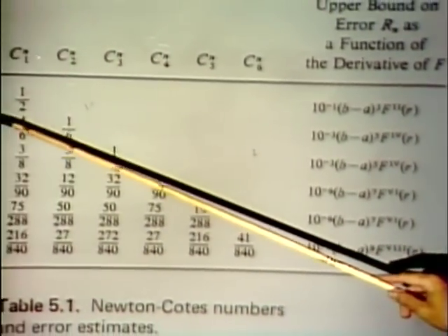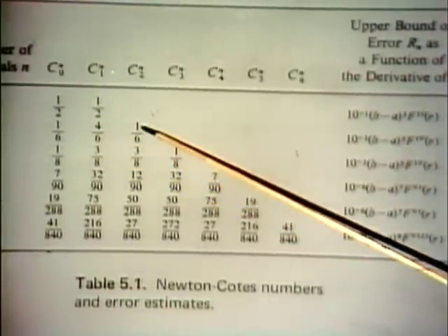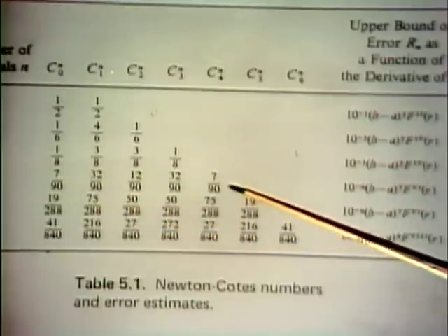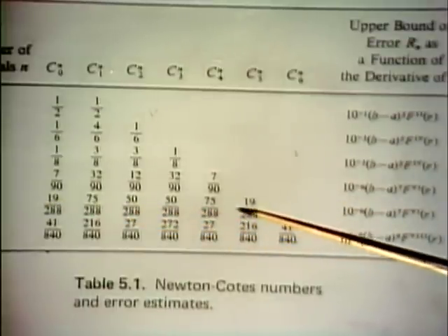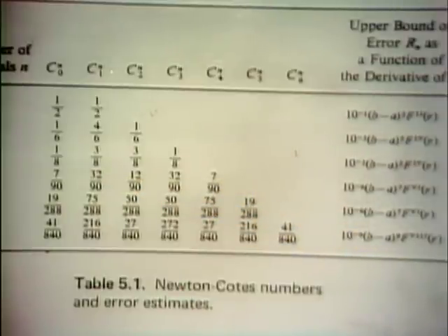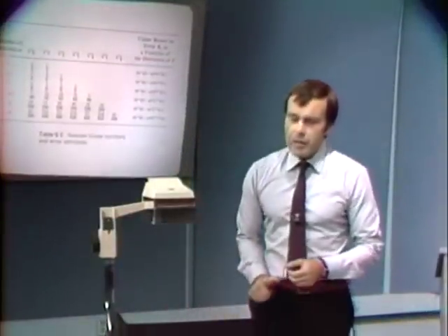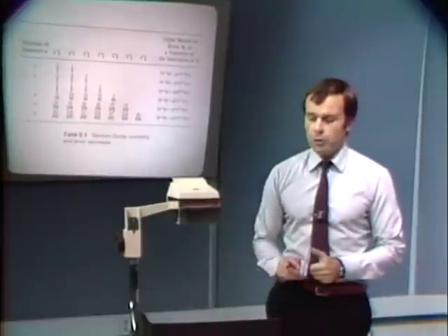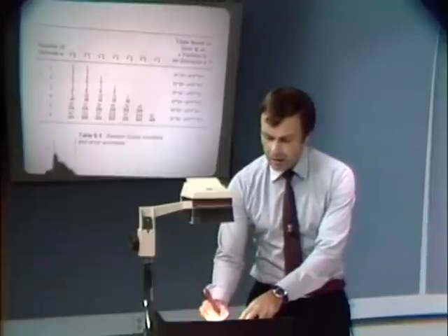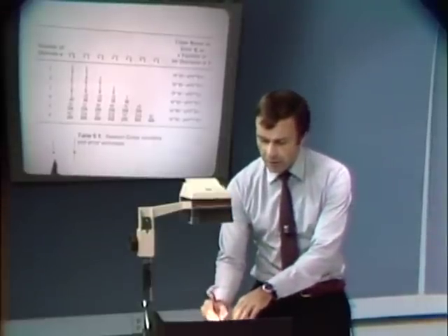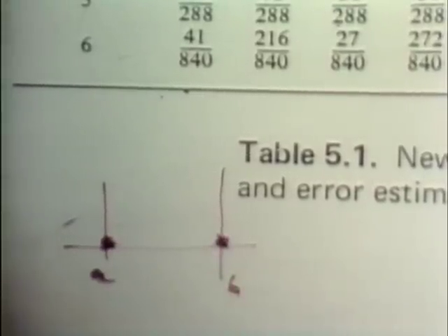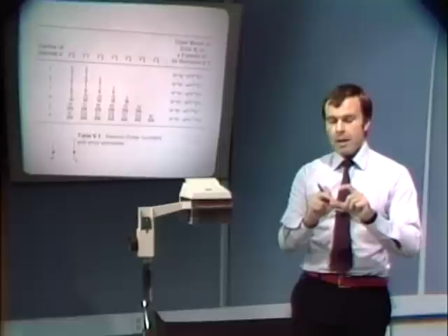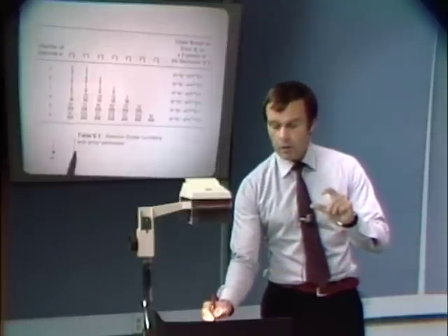In practice, however, we would only use the trapezoidal rule, the Simpson rule, and we might then still use this rule here. Notice that the error of this rule here is of the same order as the error of this rule involving 5 points. So the 4-point integration rule, of course, is preferable when you compare it to the 5-point integration rule. The other important point is that if we use the Newton-Cotes formulae, we are really always involving the endpoints of the integration. In other words, if we want to integrate from A to B, then we will involve these 2 points in the actual integration. So if we talk about the integration through the thickness of the shell or through a beam element thickness, then we would have here the top and bottom surfaces involved.